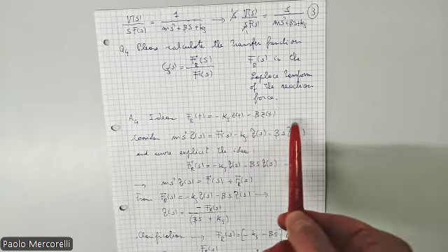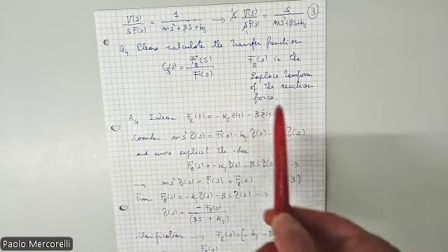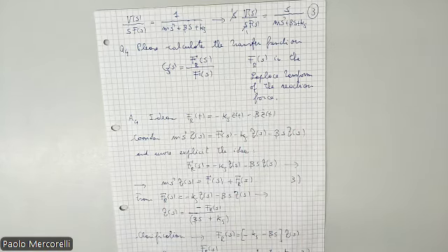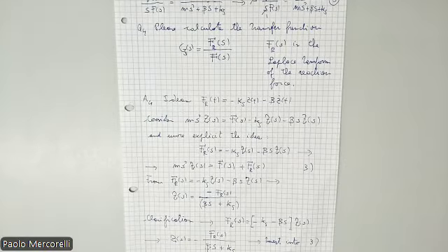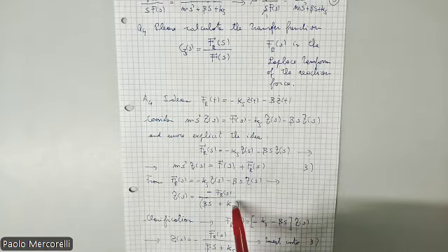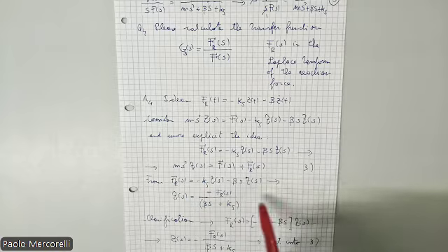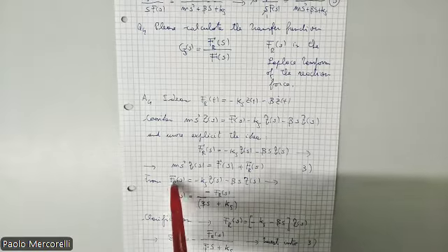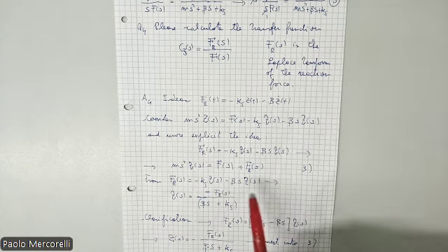Then I will reconsider the dynamics. I do the Laplace transform of my reaction force. Just looking at the reaction force, I can calculate Z of s. Is this clear? This expression is the result of this. I can write here Fr equals Z of s, which multiplies beta s minus K s.